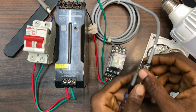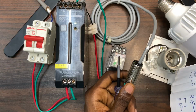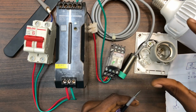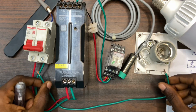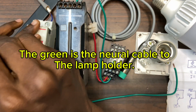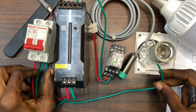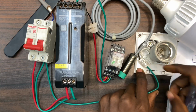Now, we want this AC load. This lamp you see here uses 230 volts. That is the live and the neutral. So in order for the lamp to work, you have to supply live and neutral cables to the lamp holder terminals. What I will do is to connect it from the neutral side of the circuit breaker to the lamp holder. From the neutral side to one terminal of the lamp holder.